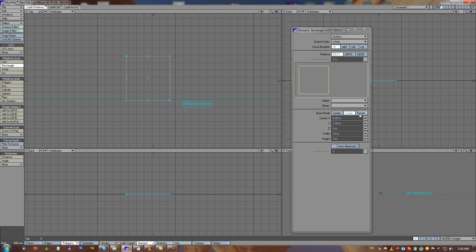And the last mode is rotate mode. We can rotate the rectangle with these 2 handles, and here we also have the automatic pivot point, which is automatically placed always to the opposite side. It is placed only on these 2 corners, but we can flip it just by using another handle, and the automatic pivot is placed into the opposite side. These automatic pivots on this rotate and corner handle are very useful when using parameters from numeric panels.